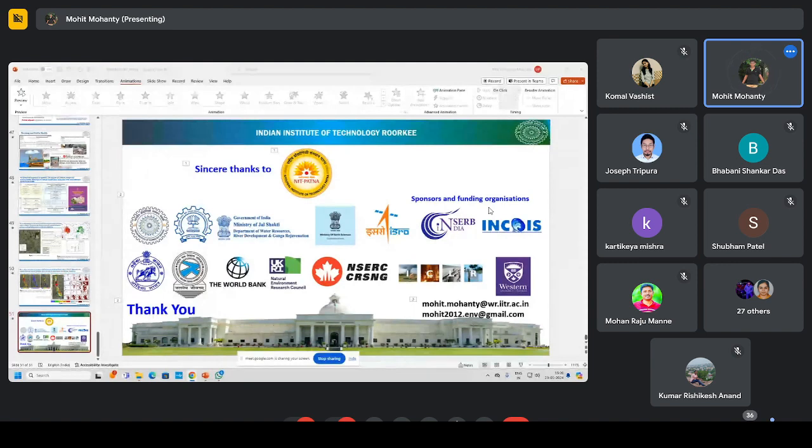How far is hydrodynamic modeling suitable for urban flooding? Okay, so for the hydrodynamic model for urban flooding, we did the flood analysis for the Mithi catchment in Mumbai and also for Delhi. First of all, for any model, be it a hydrodynamic model or any kind of model, or even an instrument, we have to calibrate and validate it.